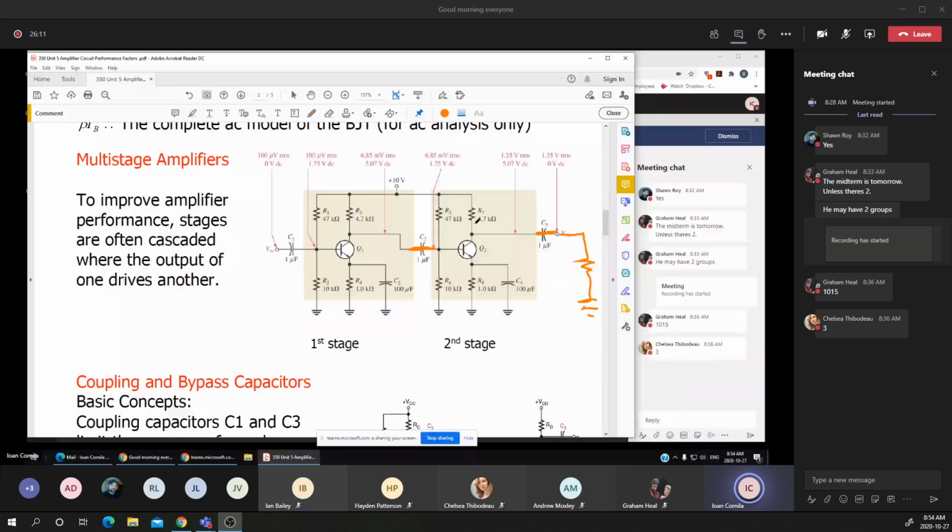The current that flows to R5 is split in two currents. One current goes through RL, the load resistance, and the other current goes between the collector and the emitter. Means that the load resistance may change the Q point, and this is what we try to avoid, to maintain the transistor on the load line without changing the Q point or the steady value of the collector current.